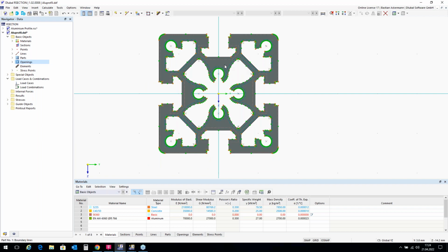So now you can see, if you would have said, okay, I want to have the thin-walled analysis with a cross-section classification of elements, it's quite hard to do that because I have a quite irregular cross-section here. I could say this could be an element here, but the next ones would be quite hard to define. So this example is very useful to use the finite element calculation as a method here.